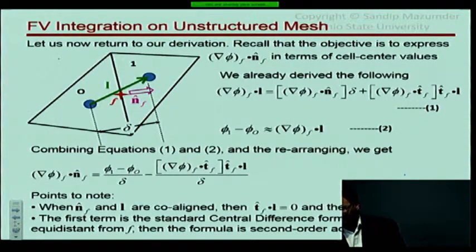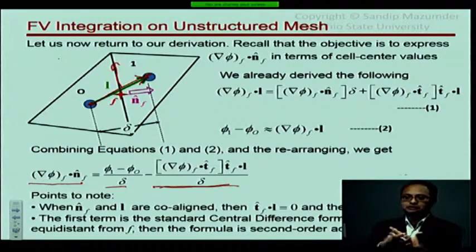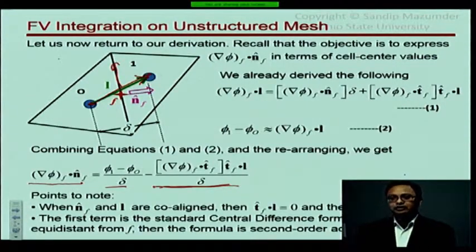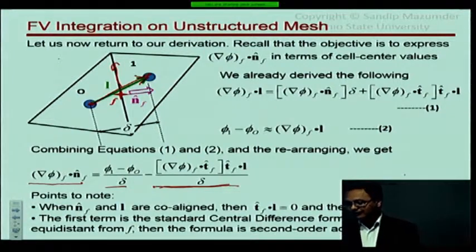What we have done here is we have taken a vector, okay, and we have decomposed it into two parts. One that is joining the vector between the cell centers, and another one, this guy here, is sort of like a tangential component of that vector. Okay, we often call this the tangential flux. So we've basically decomposed the flux into a normal flux and a tangential flux. Okay, later on in the next class, I'll show you that the treatment of this is done explicitly.